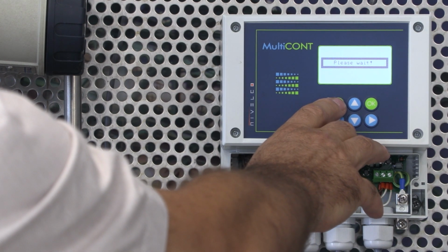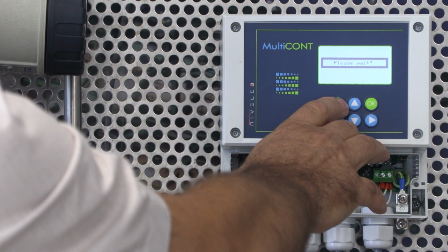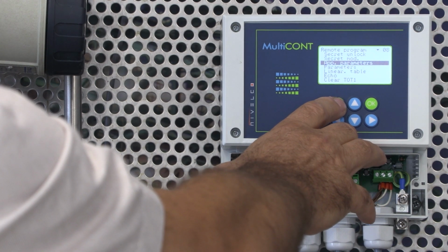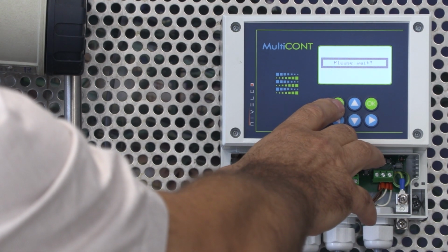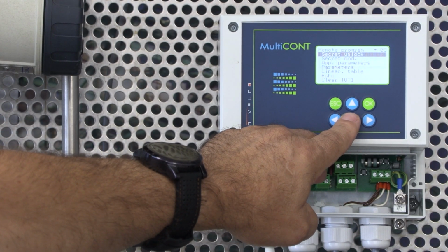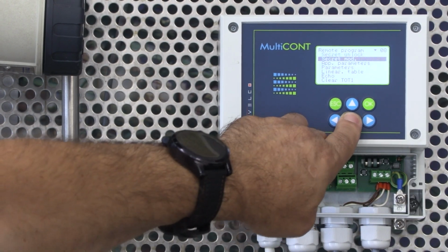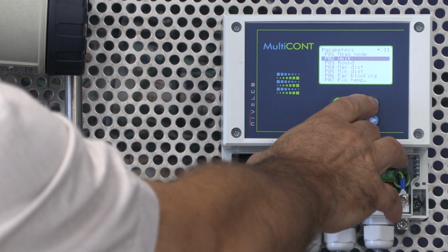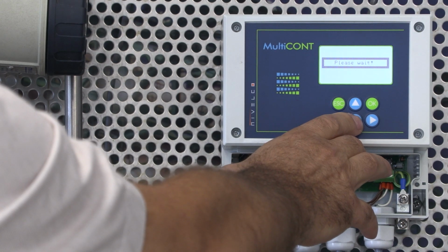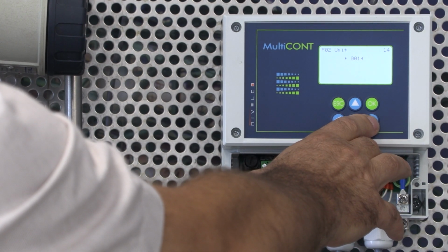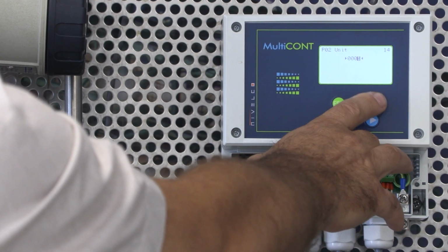It is important to note that when the P00 is changed, all device settings will revert to the factory default. Select Remote Programming to check them. Select Parameters. Then select P02. Make sure that the value is set to 0001, which stands for Fahrenheit. Then press OK to save.